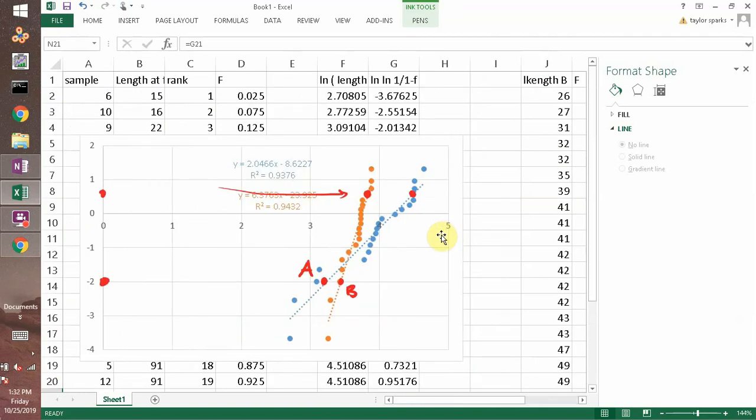So any questions so far on this? This is pretty useful because instead of relying on gut feelings, all of a sudden for any arbitrary failure rate, you know exactly the conditions that probabilistically will get you there. We've already said that this is only as good as the fit to your data, and we don't have perfect fits, and it scales. Your confidence in this prediction scales with how many test points you did. 20 is sort of the minimum.